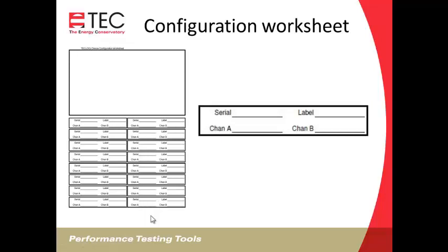If you go beyond 16 DG700s, you would need to run 2 versions of TECTITE on your computer, or run TECTITE on multiple computers to be able to do more than that. So the information you need to enter into TECTITE is the serial number of the DG700, because the software will recognize the gauge by its serial number, and then give that DG700 a label based on where it is, or what it's being used for.